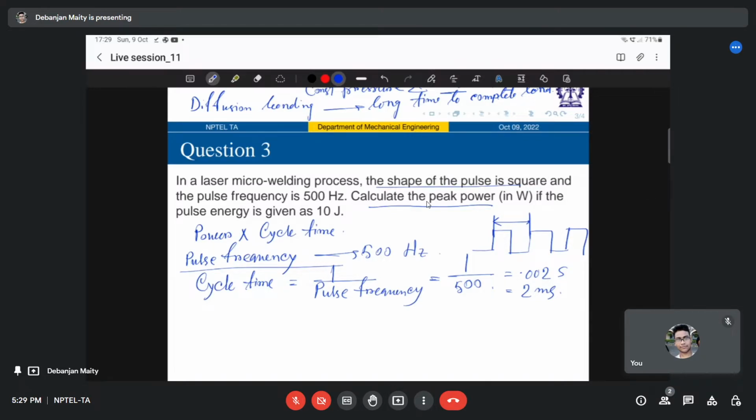So what can we tell about your pulse energy? If we know the power and if we know your cycle time, and if you multiply that, power is in terms of joule per second, that into cycle time will give you the pulse energy.